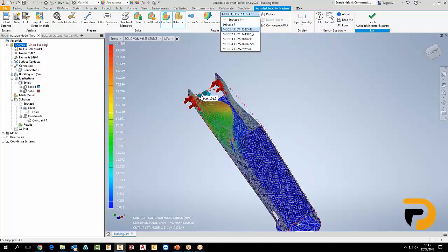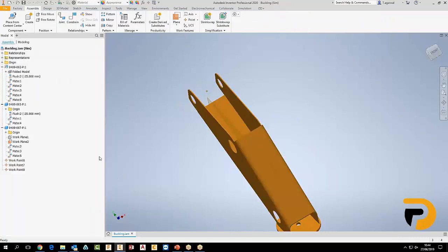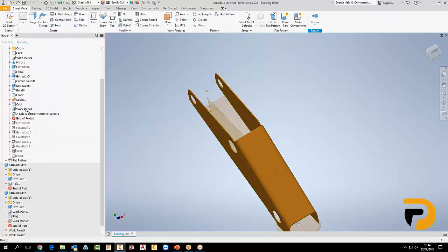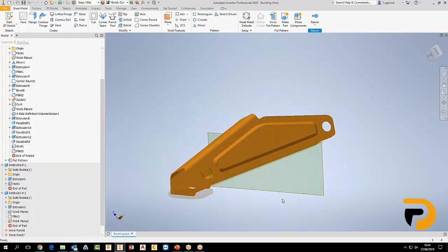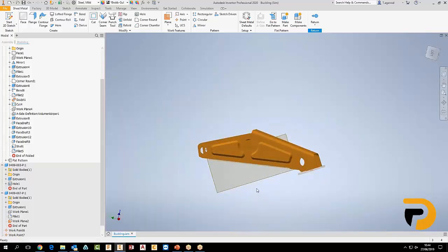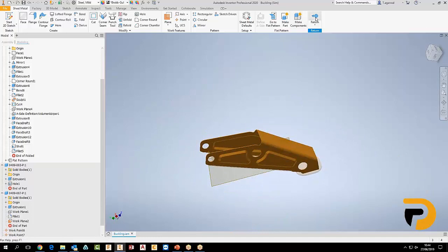And these are the 5 loads, but I already said the first one is the most practical one. Let's suppose there's a company who wants to design this component not to fail under 20 kilonewtons. Now this definitely says it has failed. Then what do we do? We finish off in Nastran, we have seen it's failing. We go back to our part and change it. I have done it already. We made some modifications, including new materials, new areas, and some extrusion just to increase the strength of the part.